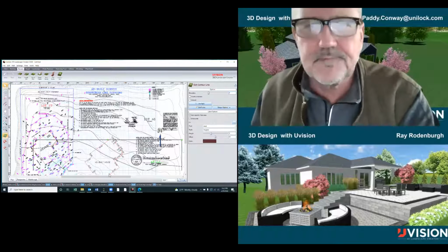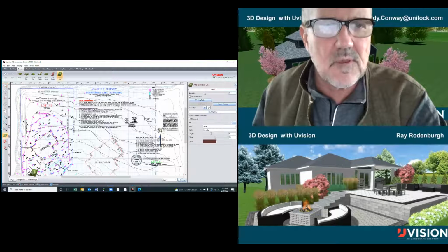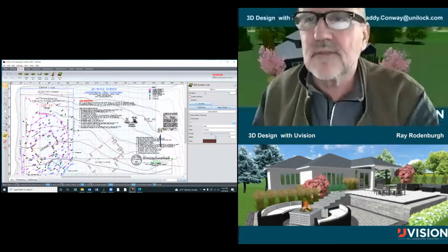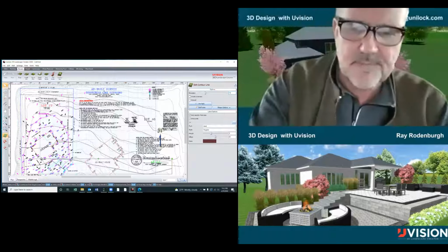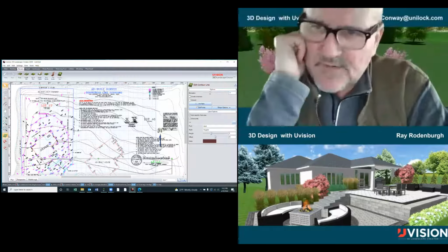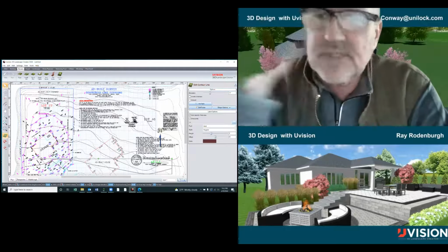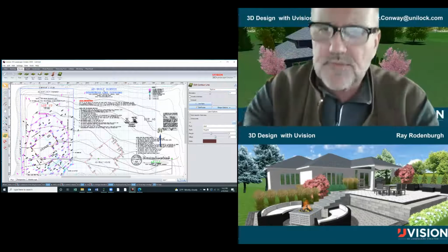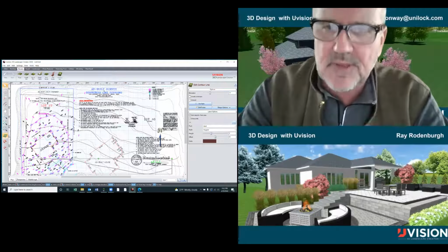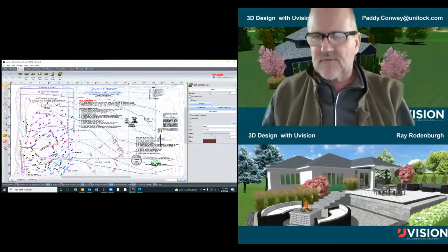8 feet. And then I will now go my last contour. Right click, and I'm going to make this 12 feet just for the heck. But generally, you can see I didn't start at 670 feet above the grid. I started at 0, and I looked at the difference between the grids, and I just calculated what this surveyor broke his increments into. And they generally stay in an increment from start to finish. So they won't start at 1 and then have 5 in between.